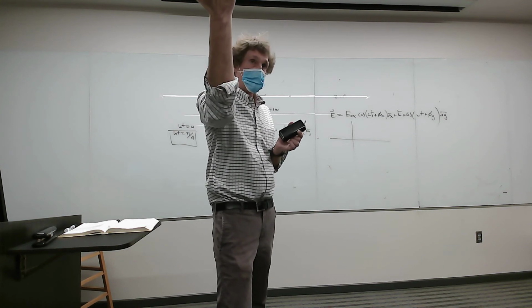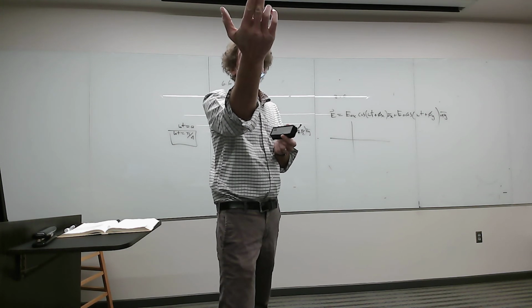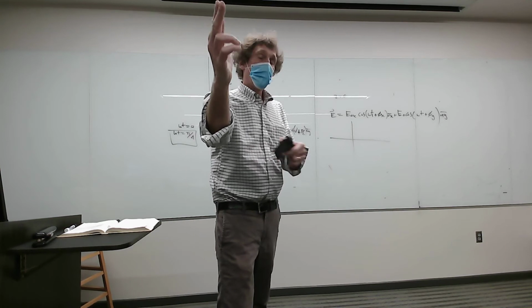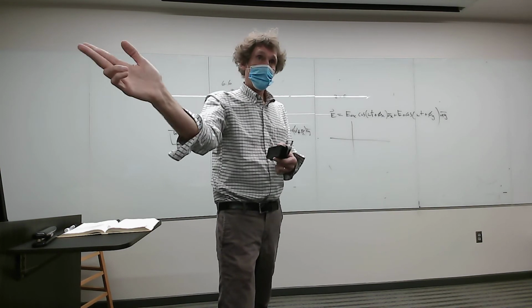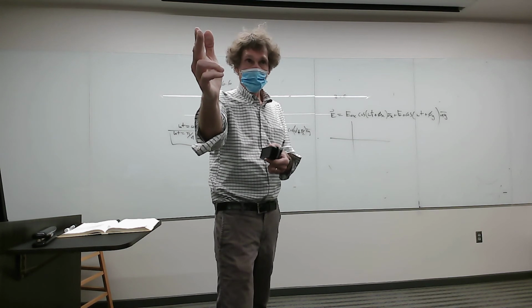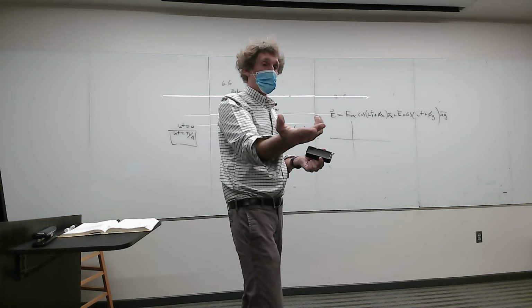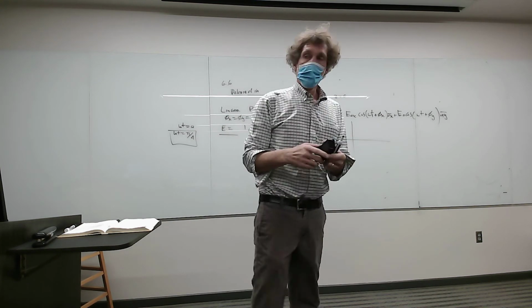It's called elevation. It's really the boresight, but elevation, and then they have azimuth. And that is how far on the projection on the horizontal plane you are in one way or the other. So you could be 30 degrees plus azimuth, means this way, 30 degrees negative azimuth this way, and I'm talking from experience now from the radar world.